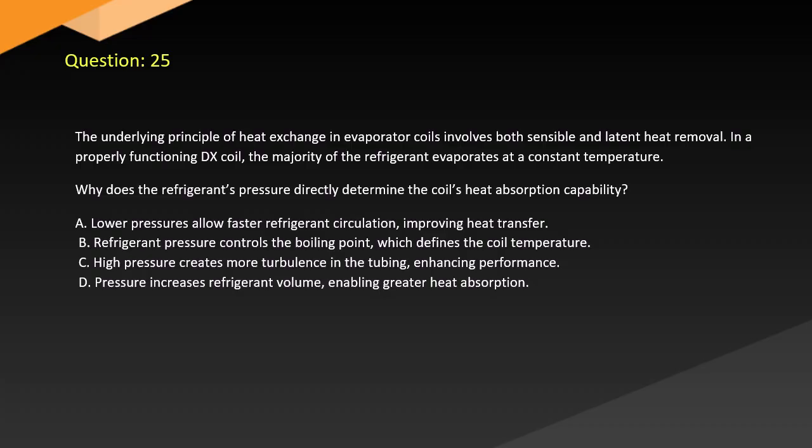Question 25. The underlying principle of heat exchange in evaporator coils involves both sensible and latent heat removal. In a properly functioning DX coil, the majority of the refrigerant evaporates at a constant temperature. Why does the refrigerant's pressure directly determine the coil's heat absorption capability?